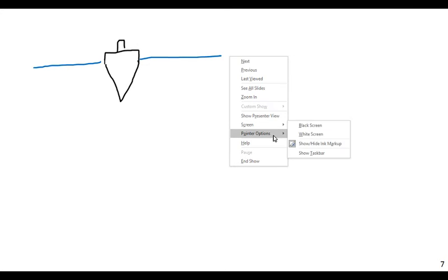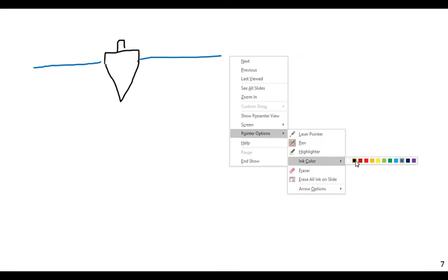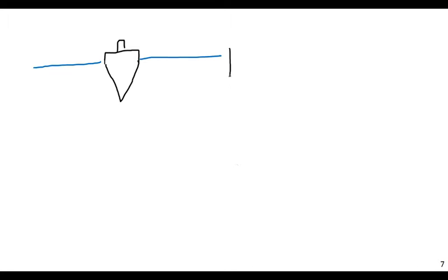Well, one big disadvantage of that is, look what happens if I design my ship to do that. This would be an example of a ship that has a lot of mass and buoyancy below the waterline. It would be something like a barge. But the downside of this is it's not going to be very stable in the water. It's going to generate a lot of drag.